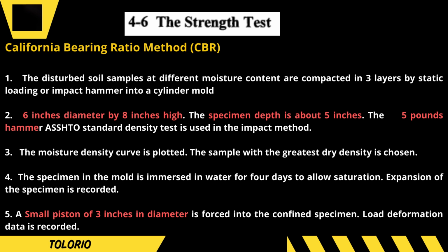2. The moisture density curve is plotted. The sample with greatest dry density is chosen. 3. The specimen in the mold is immersed in water for 4 days to allow saturation. Expansion of the specimen is recorded.